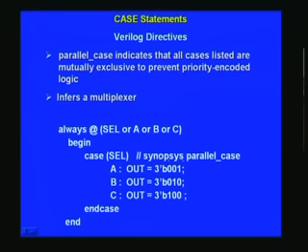And notice that with full case and parallel case, it is not a must that you adopt this. If you are not happy with it, you can refrain from using them and use the conventional method which has been already covered in the first, second or third lectures. Another point about full case and parallel case is that these directives may not work in some systems.